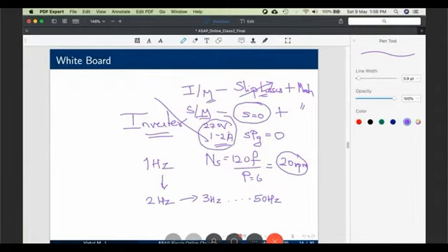Now we can get rid of the excitation loss as well. How? Replace the existing rotor with a permanent magnet. Then since there is no DC current going into the rotor, the excitation loss also is 0. That's why the PMSM is said to be the machine with the highest possible efficiency. So it's a permanent magnet synchronous machine. With the permanent magnet, I am making my excitation loss also 0. Slip loss is anyway not there. Clear?